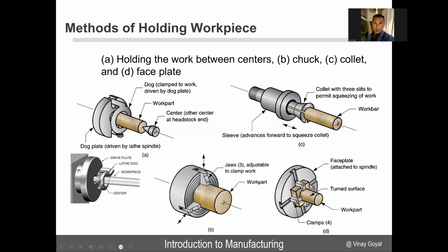In this case, it's a bar. By pushing the sleeve forward, it compresses onto the material, allowing it to be held in place for then doing operations.